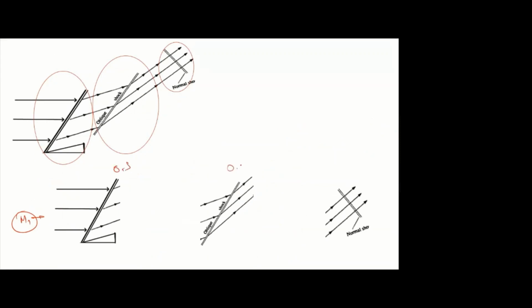Don't forget. Not only oblique shock, whatever the shock wave, oblique shock or normal shock, always start the case with the local Mach number M1. From that Mn1, Mn2, M2. Then here also start with the local Mach number M2, from Mn2, Mn3, then M3. Then here also the local Mach number directly, M4. Don't forget. Always it should be the local Mach number M1, M2, M3.